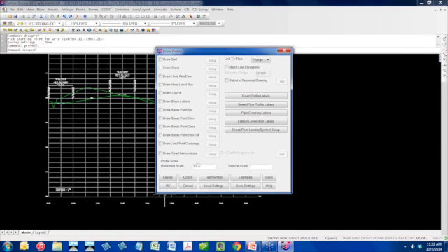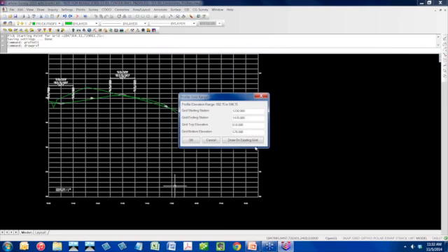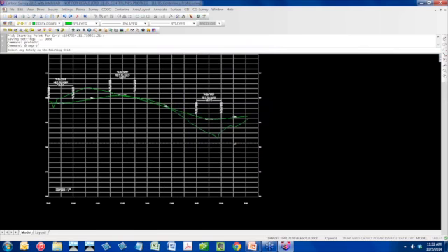When I do that, it's going to completely ignore whatever scale settings are here or anything like that. Pick OK, and notice the magic button here is Draw on Existing Grid. So all this is going to be ignored, and it's asking me to select any piece of the existing grid. So select any entity on the existing grid.